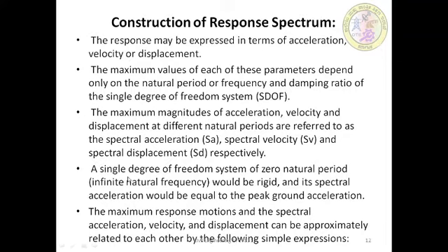A single degree of freedom system of zero natural period, meaning infinite natural frequency, would be rigid, and its spectral acceleration would be equal to the peak ground acceleration. Now the maximum response motions of acceleration, velocity and displacement at different natural periods are referred to as SA, SV and SD.